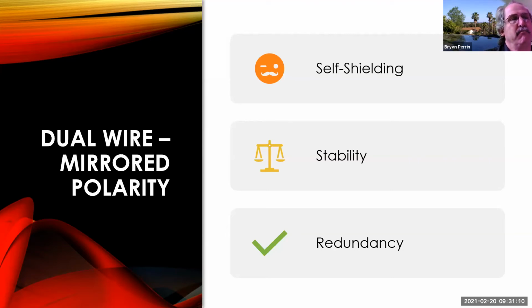So most dual wire systems are not redundant. Some will run in what's called single wire mode. I have a screenshot of a car going from dual wire mode to single wire mode on a CAN-B system, where both sides mirror each other. But on most of these systems, if I lose either high or low, I'm not talking. If I have an open, I may be able to talk past the open on the other side or get part of the message through. If it's a short, I'm probably not talking. So it depends on the type of fault. Not all faults are equal.